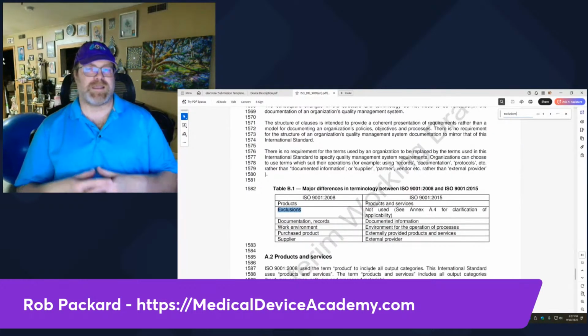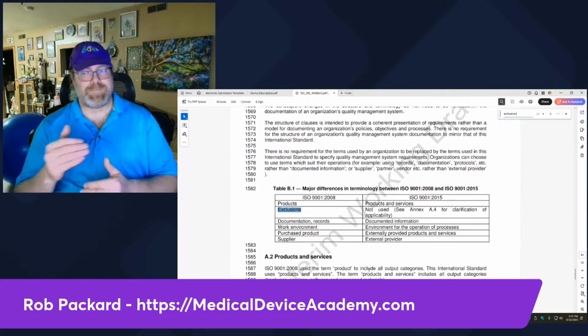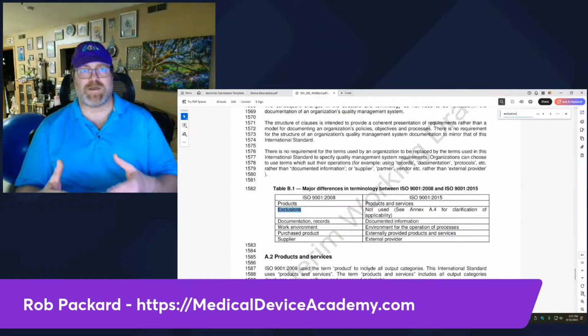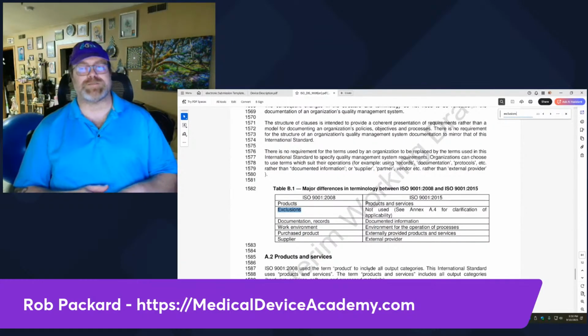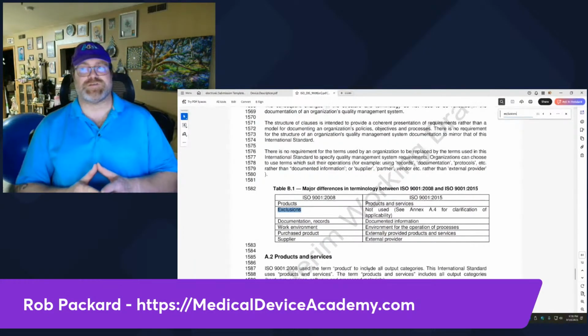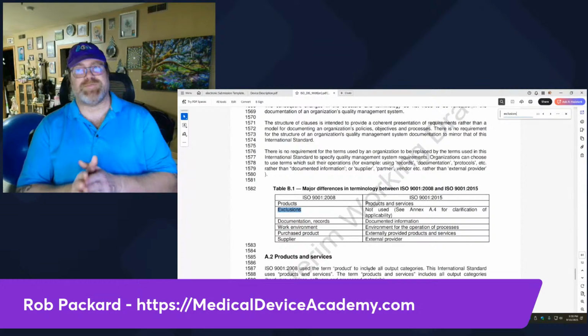And so we see a lot of companies that are suppliers that are not meeting the requirements and don't do well in inspections. So you should be aware of that and maybe have your own checklist or have very qualified auditors that know the 13485 requirements doing a process approach audit of those suppliers to qualify them and identify any gaps before you get into an arrangement where they're manufacturing your product and they might be inspected. So that's what the differences are between 13485 and 9001.